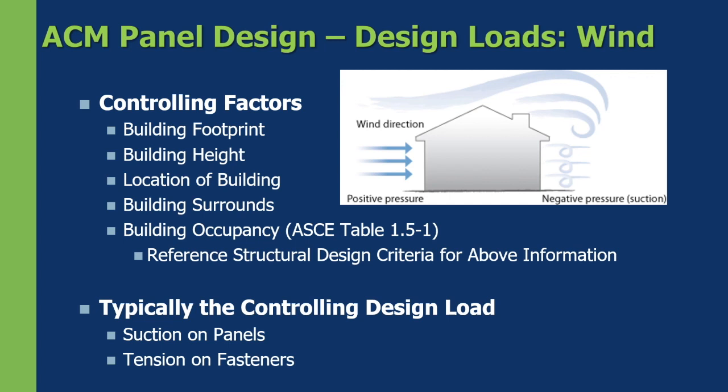And what that can mean is what was done in engineering for the previous building won't work for the current one. You may need to have a smaller girt spacing. You may need to have stiffeners on your panel. You may require more fasteners. So it's important to understand doing a side-by-side comparison of buildings doesn't always work out.